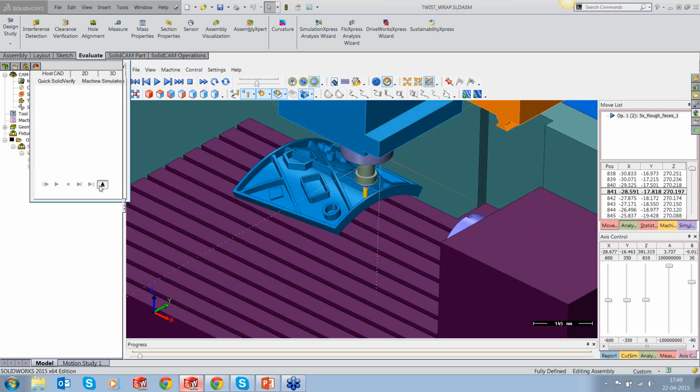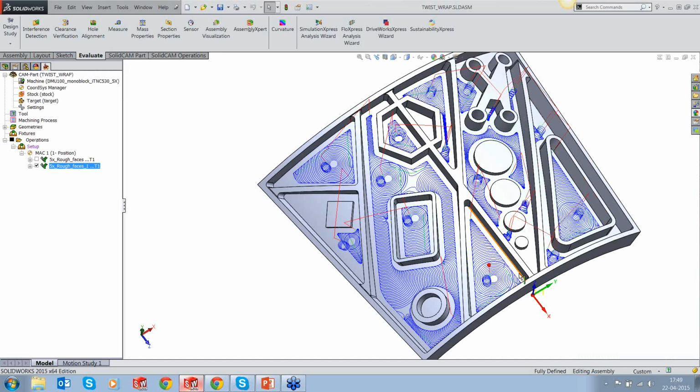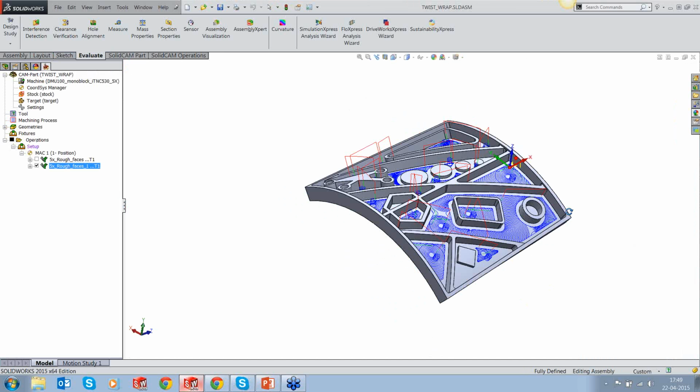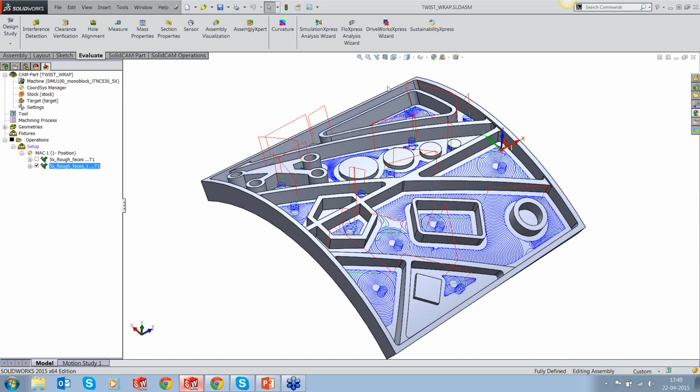Right. So the conclusion of multi-axis roughing is that whenever you have parts or pockets that you would like to rough out in one go without a change in setup, and which need more than one setup to do, especially if the walls have undercuts and stuff like that, you can easily use multi-axis roughing.